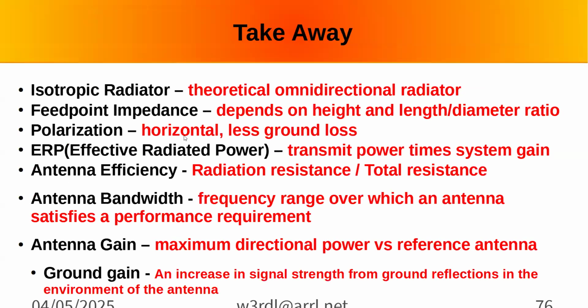So we talked about isotropic radiators, feed point impedance. It depends on the height and also the length-diameter ratio of the antenna elements. Yes, as you change the diameter of the wire, you will affect the velocity factor.